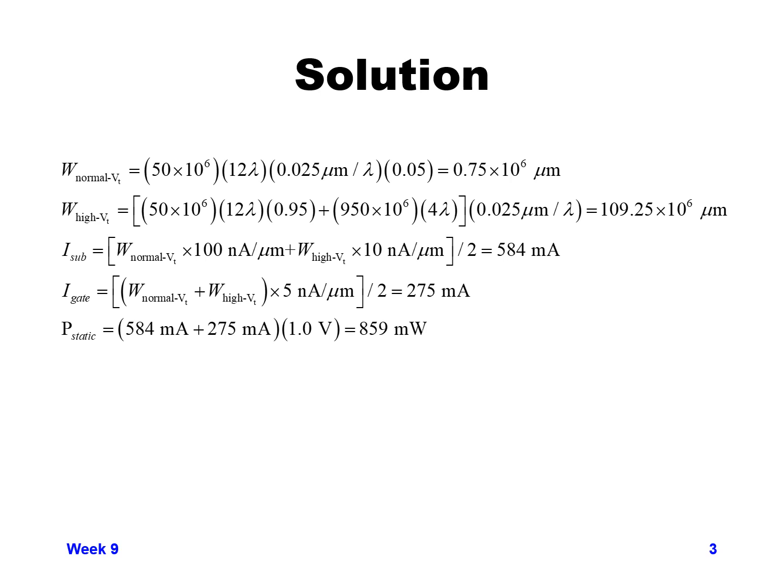The PMOS gate isn't leaking because the gate is tied high and the source is tied to VDD, so you don't get leakage through that. Whereas the NMOS device has a high voltage between the gate and the body, so the transistor that's turned on has a high voltage across it and has the high leakage. So only on average half of your transistors have gate leakage going through them.